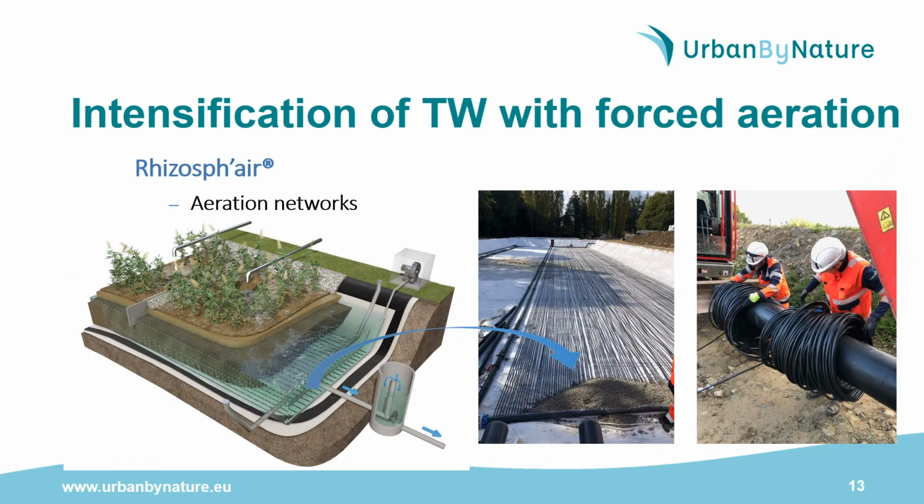Concerning the intensified wetland equipped with forced aeration, the principle is still the same as the French design because it receives raw sewage directly on the filter surface. But here the filter has a saturated and aerated zone of 1 meter deep, as you can see on the picture on the left. A dense aeration network rests at the bottom of the filter and is connected to a blower which transfers the oxygen needed for the oxidation of the organic matter and the nitrogen coming from the raw sewage.